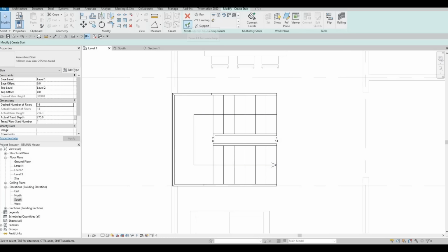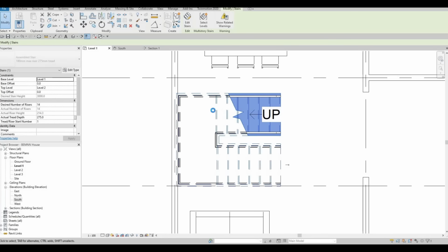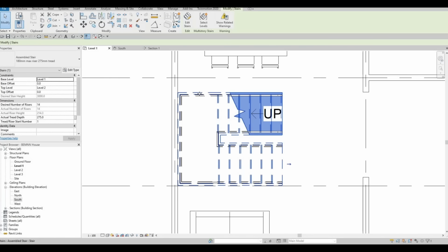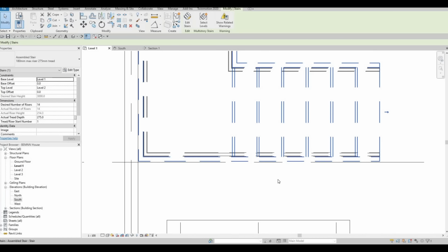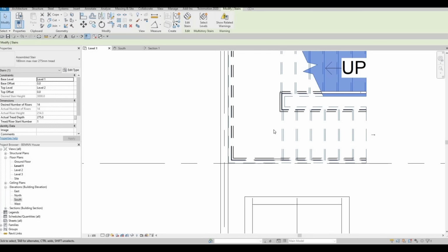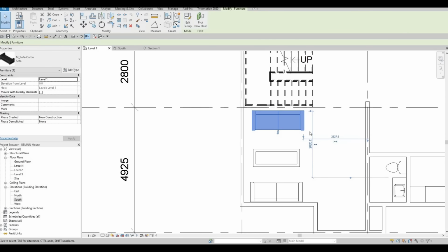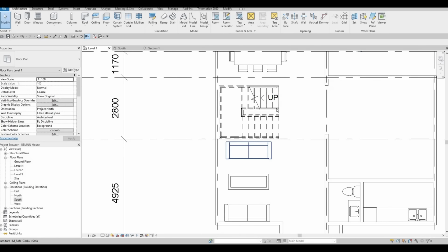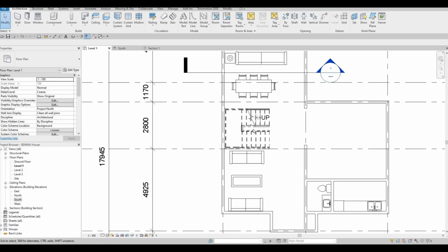What I usually do is I click on finish first. The reason for that is I don't want to ruin anything. And then now I could just use my arrow key to move it around. You can see that there are dashed lines indicating where your railings are and what you have right there. So here, this is perfect enough for me. Now I could just move this one back to make everything expand a little bit. Because for me, I was just estimating everything like that. So I have my living area here, my family area, and then my dining area right here. So everything is looking good.